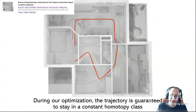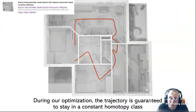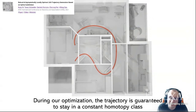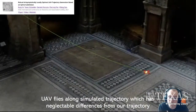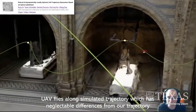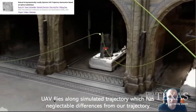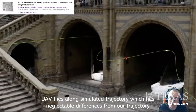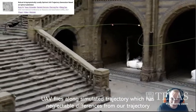In the same spirit, with a similar formulation of this idea of starting from a valid state and always keeping it valid and recasting everything as unconstrained optimization, we used a similar approach for optimization of drone trajectories. This is a paper that is going to be presented at ICRA, where we use a similar idea to optimize drone trajectories in indoor environments, and where we have strong guarantees on staying in the same homotopy class and guaranteeing to always have a valid path. And here is just an example of how this will look in a more complex scene. I don't have much more time to comment on this, but I encourage you to take a look at the paper in the top left if you're interested.